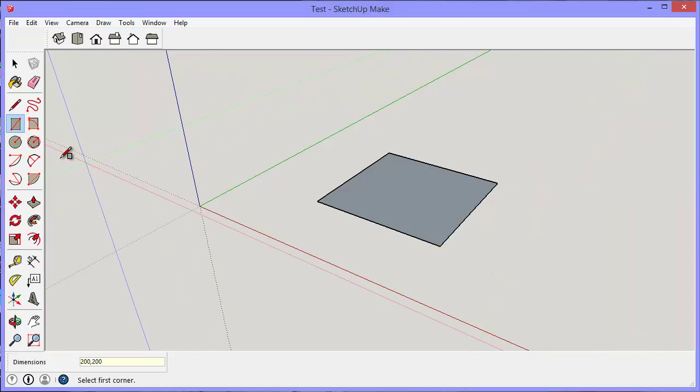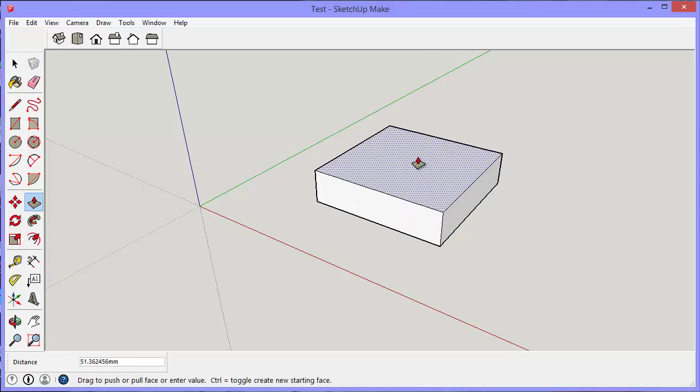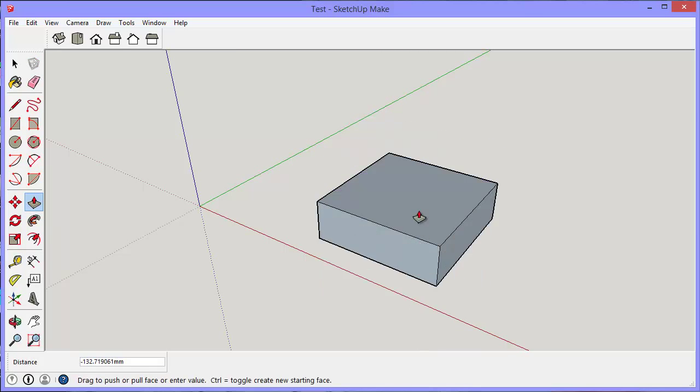That's the first tool, so this rectangle tool. Now, what I did next was I used what's called the push and pull tool. You're going to use this loads. Okay, you're going to click on that, and it allows you to select a face. Can you see that goes a different color? As soon as I click now and start dragging, I can go upwards or downwards.